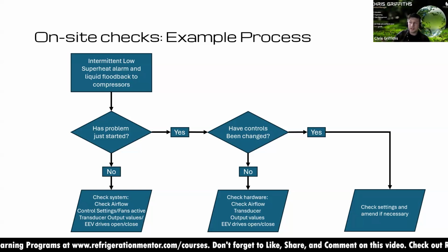If that problem has just started, next thing we check is, have the controls been changed? Try and narrow it down to whether it's a software or a hardware issue. If the controls have been changed, could well be something to do with that. So check those settings and amend if necessary. Monitor it. If the fault reoccurs, it's unlikely to be controls related.